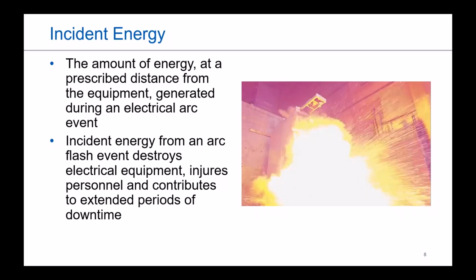It's not just a rating like you would say, like your total apparent power, like kVA, or your voltage or your current. It's specifically of what you're going to be exposed to, and the equipment is going to be exposed to if there is an issue.